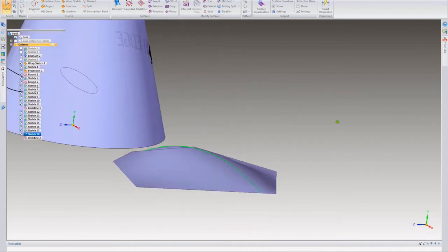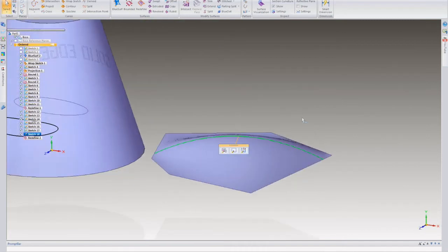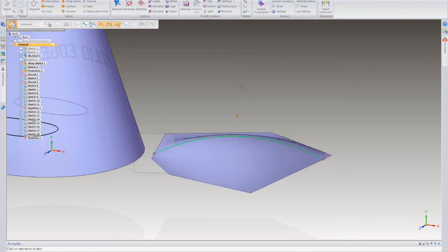And let it catch up. There it goes. So what I did is I created an open profile. I did a closed bound with the new closed bound. I did a redefined surface. I added some sketch control points. Then I can come over here and modify these control points by using the dynamic edit. So you can redefine any surface that you have, whether it came from Solid Edge or from an outside source. And I believe that takes me up to about 20 minutes. Candace?